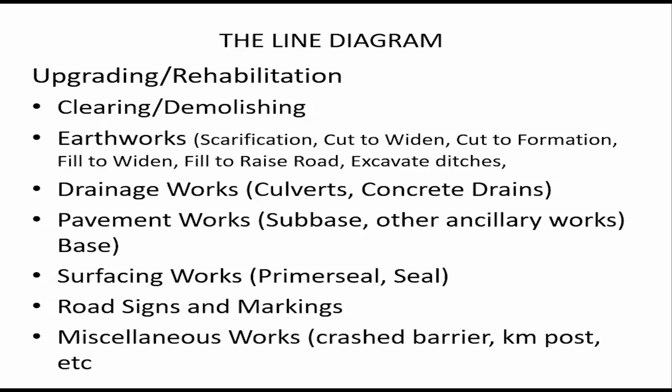Culverts and concrete drains are also involved in the upgrading works. Then, of course, pavement works, which is sub-base and base with other ancillary works. Then we have the surfacing works, that's the primer seal and seal, because upgrading is bringing the road from a gravel surface to a bituminous surface. So definitely there will be primer seal and seal. Then of course you do your road line markings and signs. Then if there are other miscellaneous works like crash barriers, perimeter posts, we put them in there.